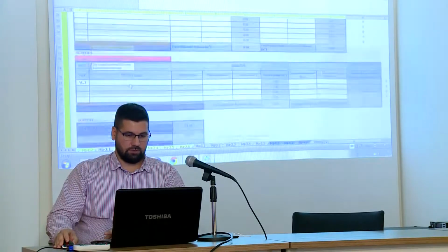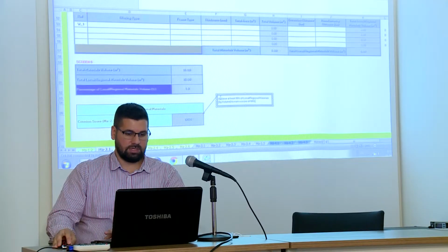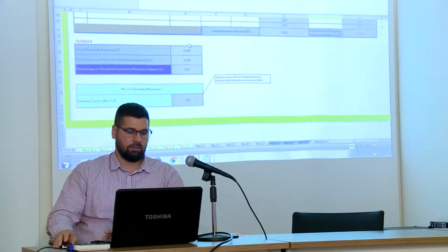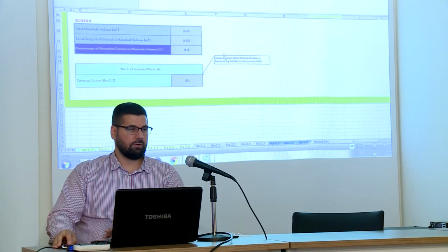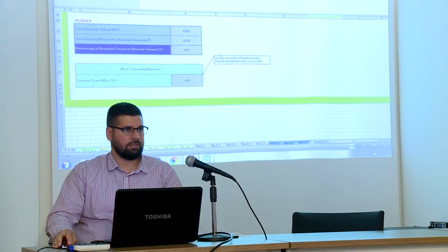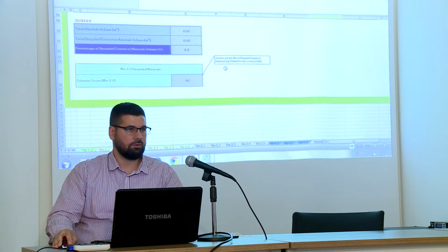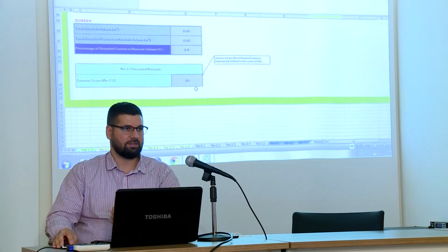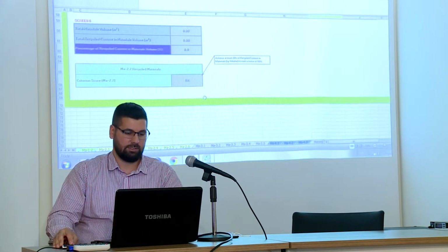So as I mentioned, for the regional, it's 90% to earn 100% score. For the recycled content, it's only 20%. If you have recycled content within the building material that reach 20% by volume, you will earn a score of 100%. Okay? Because we know it's very difficult to have 90% recycled content within building materials.